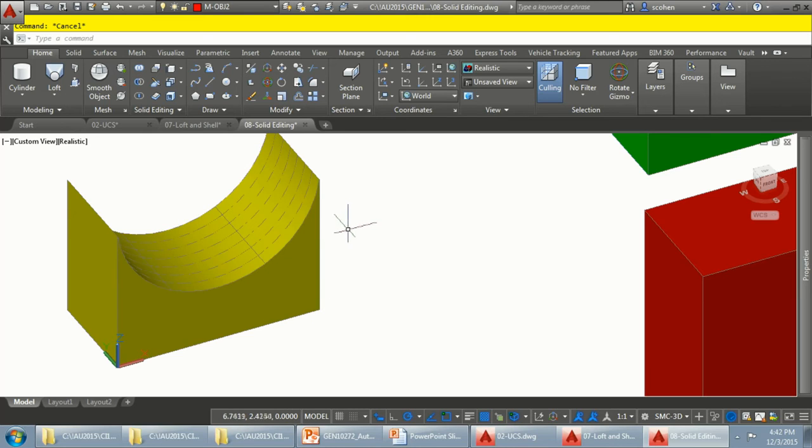So there's a variable I want to point out. You guys may or may not be aware of it. It's called DELOBJ. All right? And there are a whole bunch of settings for this variable. In fact, actually I'm not online, that's right. So I think I put it in the handout. It's like 6 settings. You have 0, 1, 2, 3, -1, -2, -3.